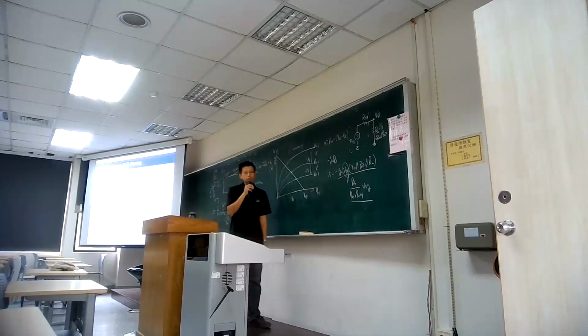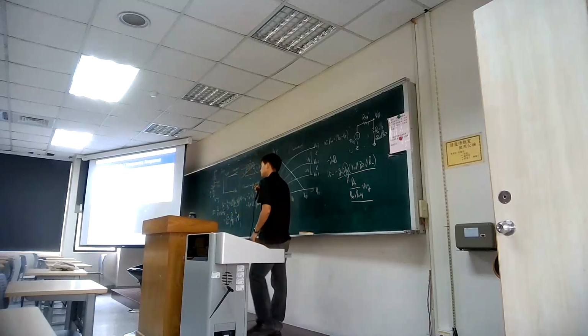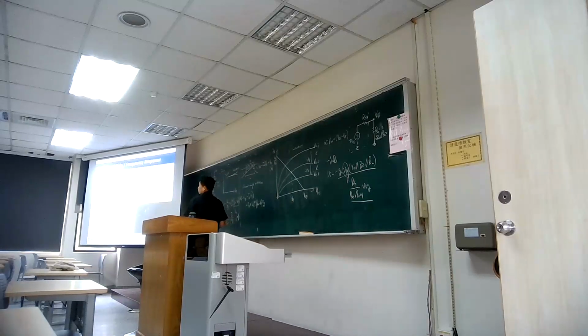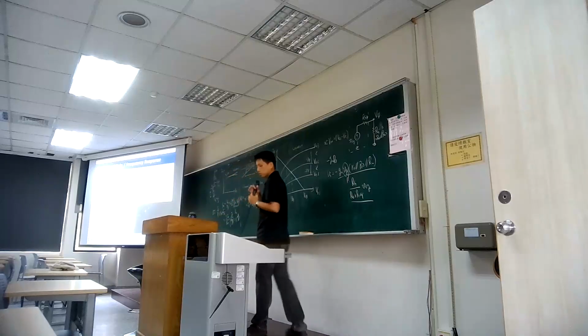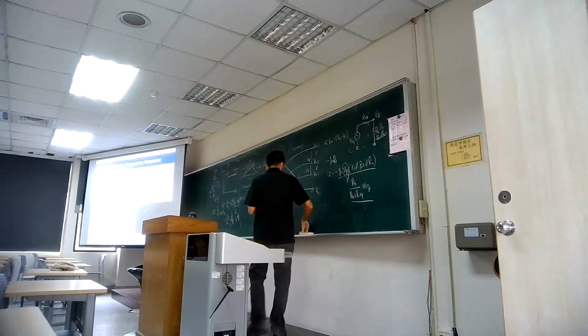And how about high frequency response? I think most of you design with ideal resistance. In PSpice, they even give you really high frequency response, so you can see the response seems to be constant. But if you are working with a practical device, we work with several gigahertz transistors. So what happens here is there will be another roll down. This roll down is induced by the capacitance and resistance in the transistor, not from the circuit. And why there is a capacitor in the transistor, that speaks about the device.